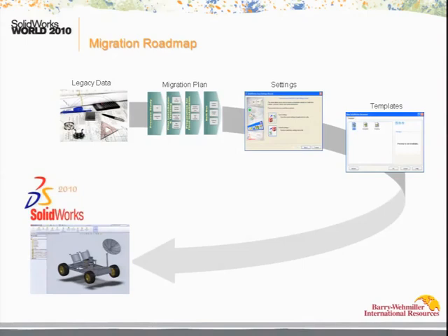defining them upfront. So, one guy doesn't write 1.5 inches and another uses a fraction. One guy doesn't write 1.5 inches and gives a tolerance of, let's say, 10 thou or something of that sort. Those are the things which are possible through settings and templates, and those should be leveraged when you move over from your current software to SolidWorks.